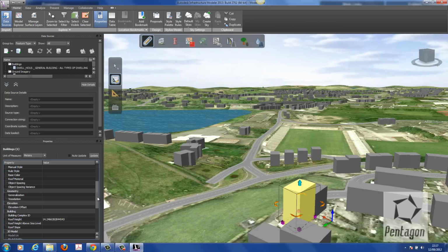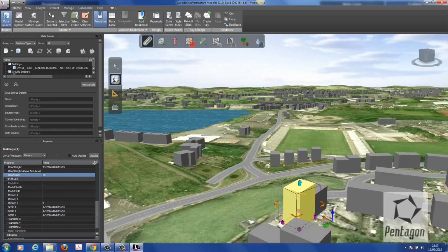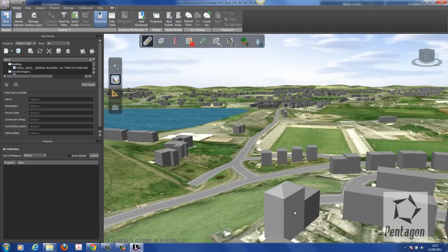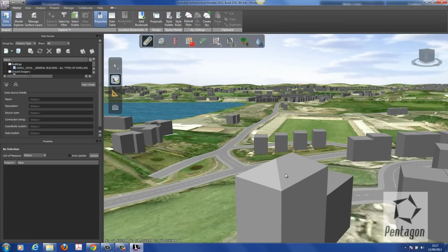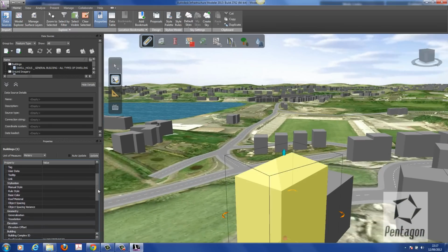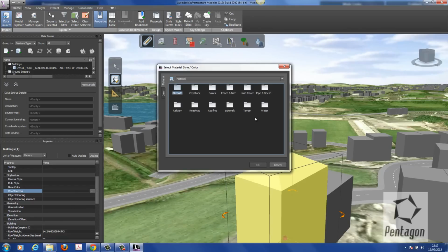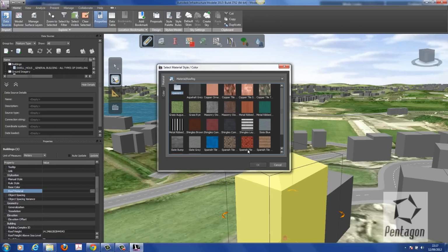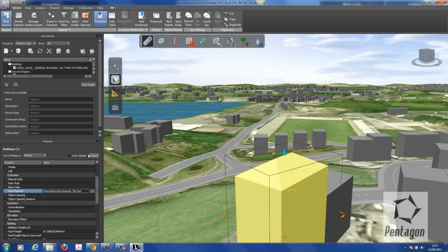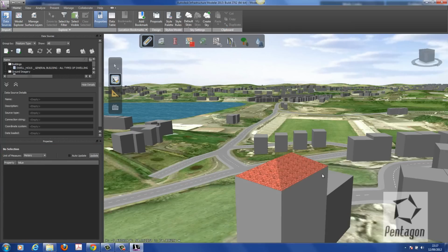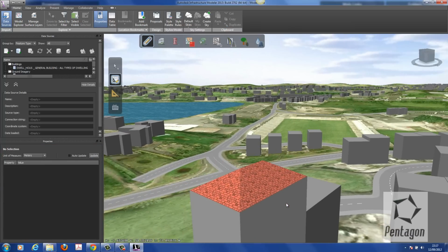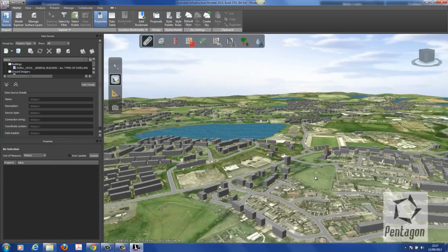So you see we've got a wealth of different information in here, like a roof slope. So I could go in here and say, look, add in a roof slope of 30 degrees. We could update that, and we've got a slight roof pitch in there, as you can see, of 30 degrees. I could add a material in against the roof. So again, we could select the properties and we could scroll down here and look for a roof material. So again, we could go into materials library and I could say roofing, and I could say we'll make this say a Spanish tile. Again, if we go update, that information will come across. It's much easier if you have a coded data set to read off, but in this sample we don't.